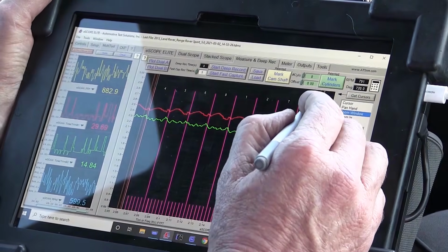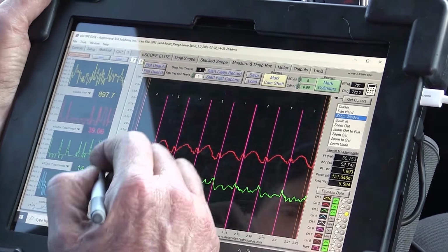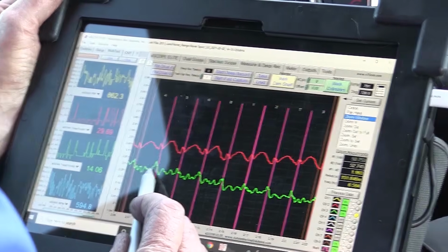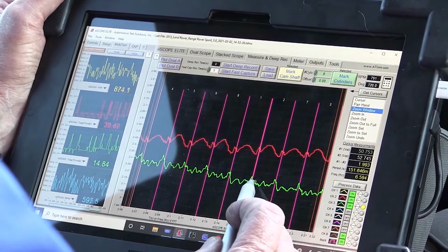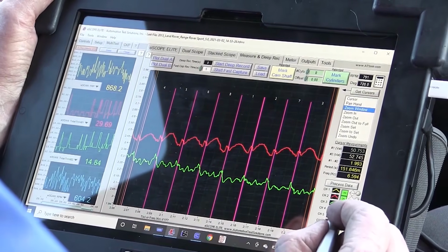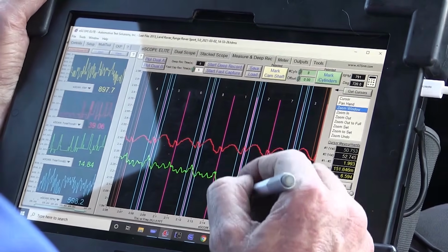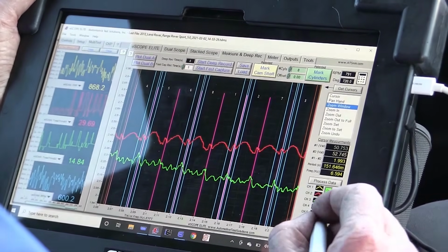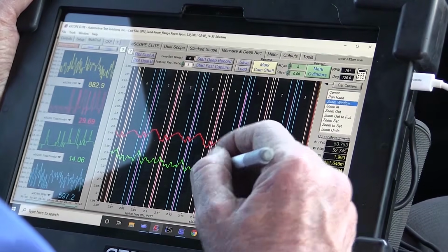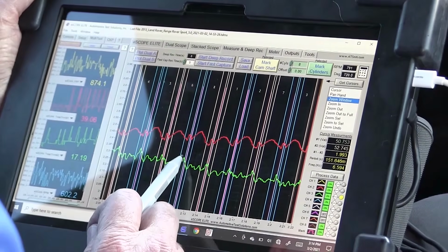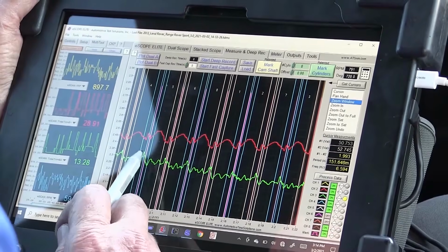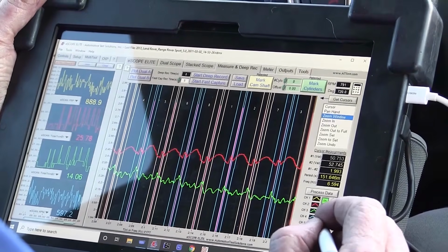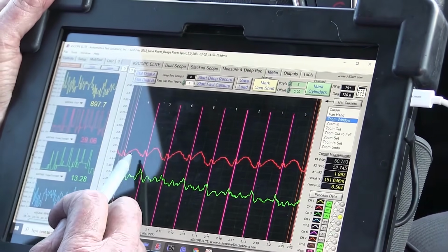So we'll take our zoom window and we're going to amplify that where we can see. Do you see how this is a pressure pulse right here? And this is, and this is, and this is. Let me turn on this. This is where we turn the pump on, and this is the other position we turn the pump on. You can see that those correspond to these little rises in the high pressure line. This is the high pressure line.